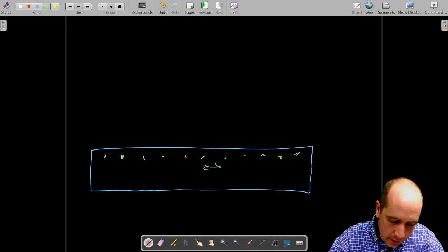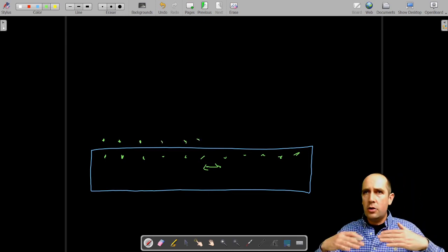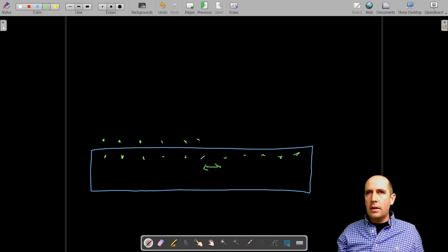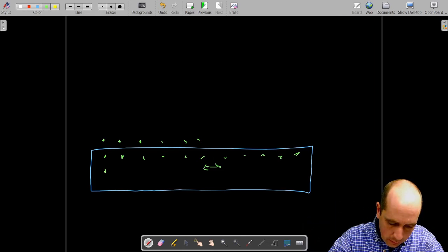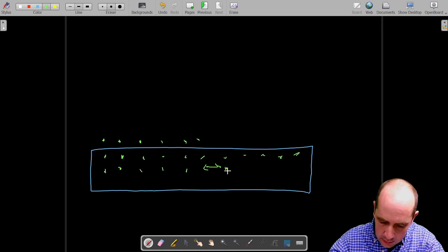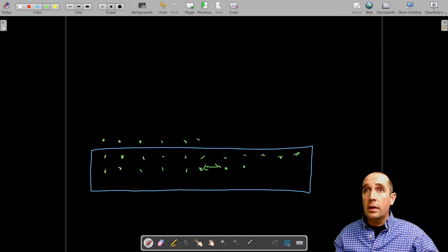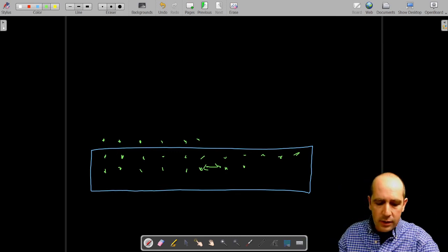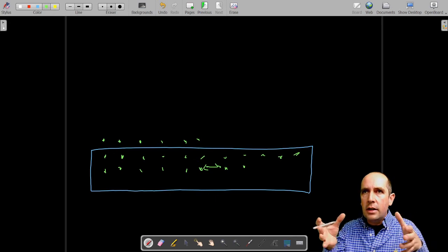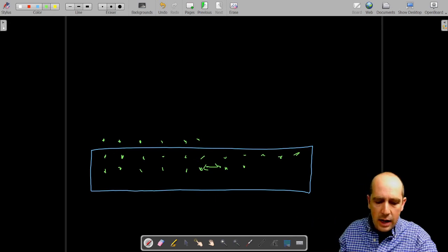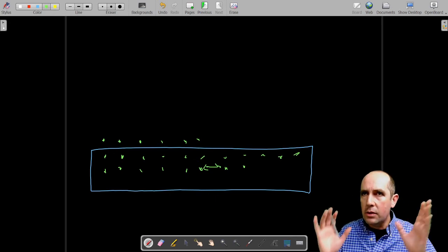And the silicon atoms will tend to align with these ones and produce a nice lattice that just replicates the same lattice that we had below. So if we had this lattice below, the silicon will tend to just continue growing in the same exact crystallographic direction. And since this is the natural spacing between silicon atoms, all the lattice is relaxed, everything is okay.